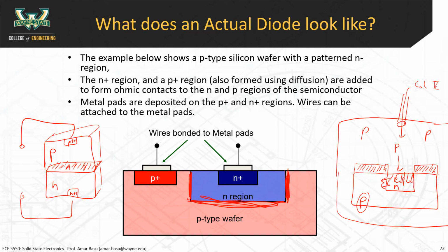So in practice, when you're calculating the area of a diode, the engineer lays out what the structure is going to look like from the top. Your process engineer figures out what the junction depth is, and from that you can figure out the area of the diode. So this is a process that's used to make diodes. A similar process is also used to make solar cells.